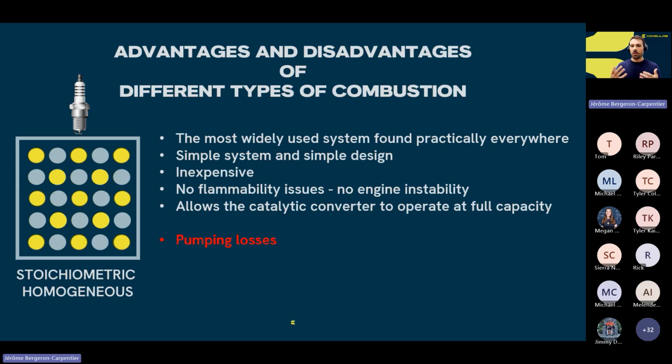By closing the throttle body, we prevent too much air from coming inside the engine, and the engine is basically a vacuum pump in a way. With the throttle body closed, we have pumping loss, so the engine is working and trying to fight that pumping loss. Basically, there's some energy loss in that concept.